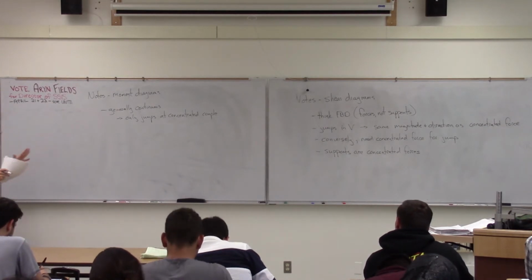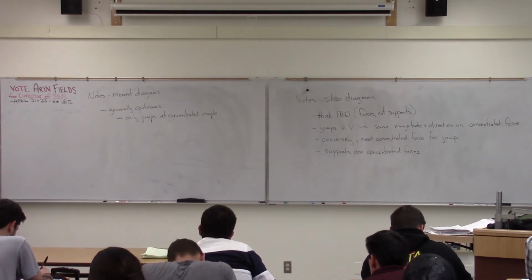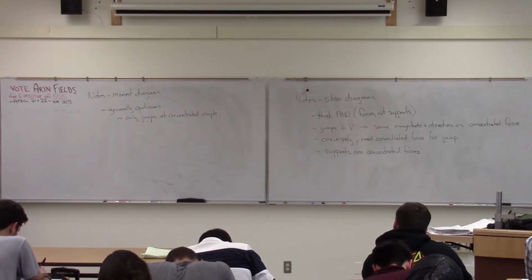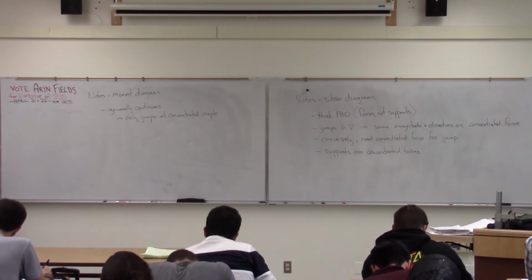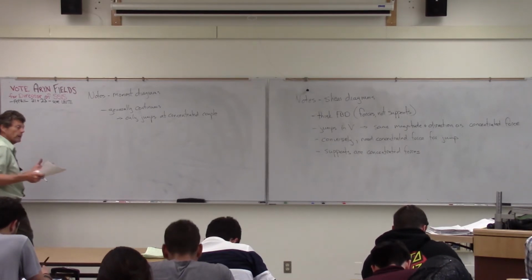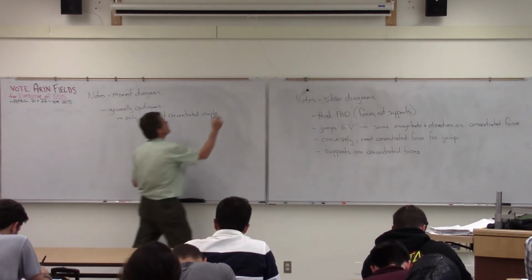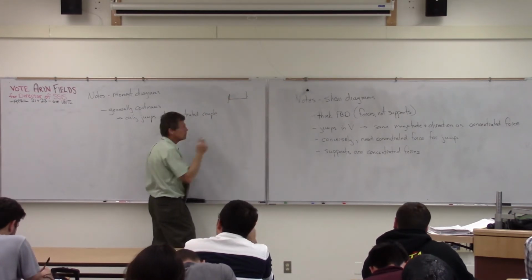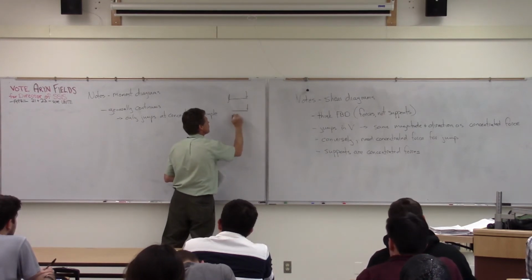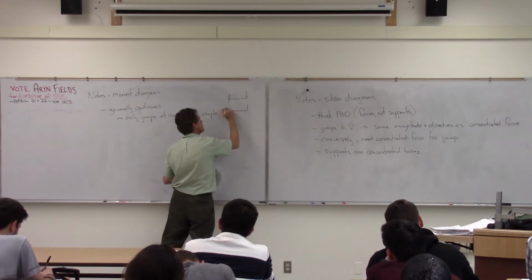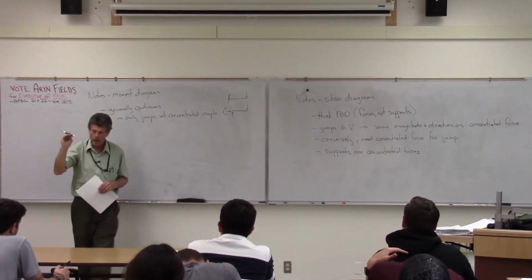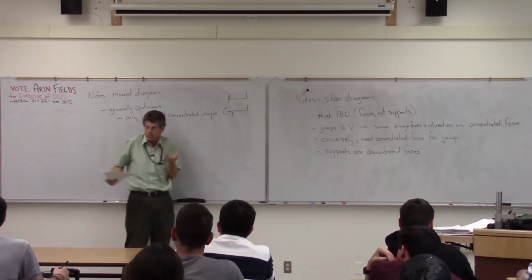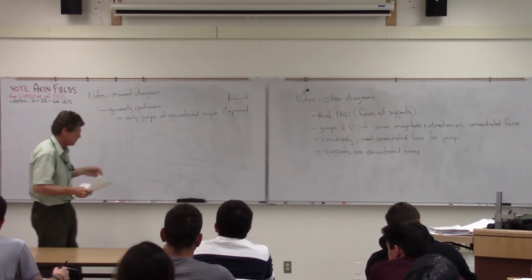Okay, moment diagrams are generally continuous. The only time you'll see a jump, and we had it in our example here, is when you end up having a concentrated twist. Now again, that concentrated twist can be out in the middle, or it could be at the end. When you think about a beam like so, a built-in beam, again, think about your free body diagram. Force, force, force, moment. So you're going to have a concentrated twist at the end of that particular one because there is a concentrated twist created by the support force.